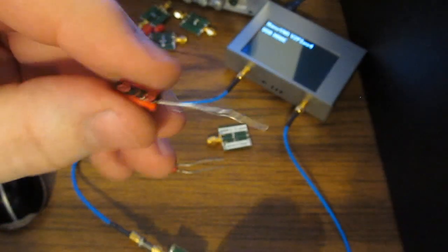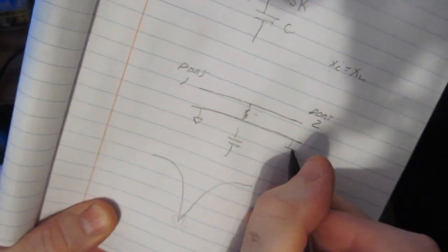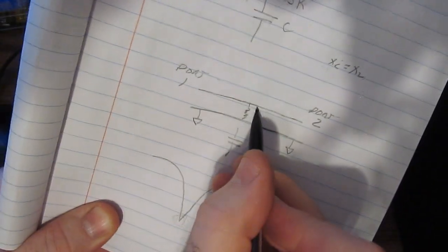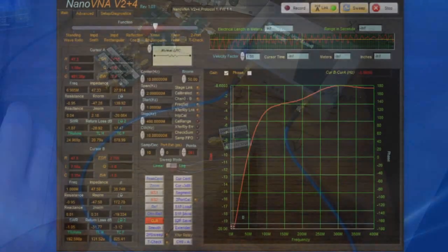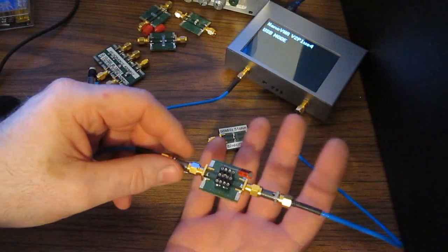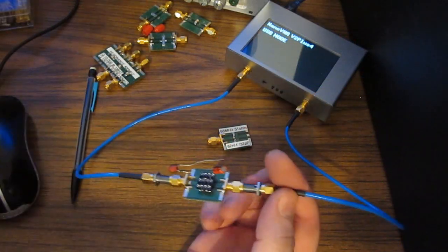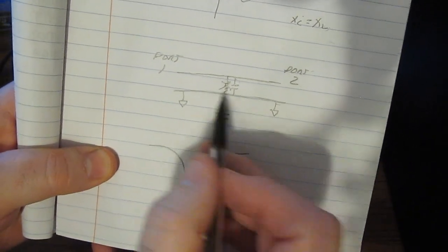Let's just go ahead and attach our aluminum electrolytic. Again, this is our ground on the 2 sides of the Nano, and the capacitor is sitting right between these 2. And we can see there's this definite dip down here, and we are calculating with this capacitor roughly 2.8 or so ohms of ESR. Now, to be clear, there's some problems when you make measurements like this. First of all, you'll notice that there's this ground loop between these 2 connectors.